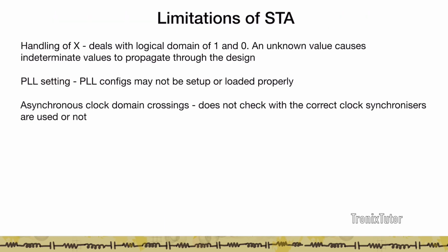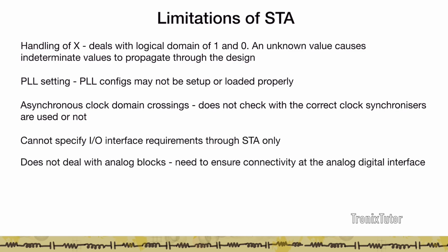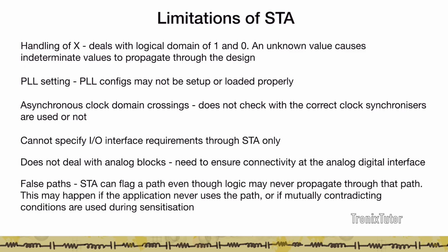Now before we close, let's talk about the limitations of static timing analysis. STA obviously has to be used carefully. You can't expect it to give you answers for all the timing issues in the circuit. First thing, for example, would be the handling of tri-state. STAs normally deal with logic domains of 1 and 0.